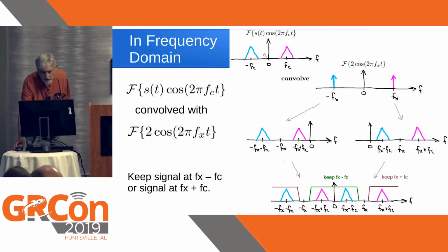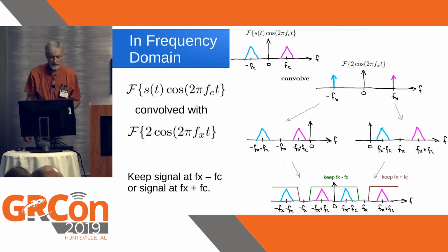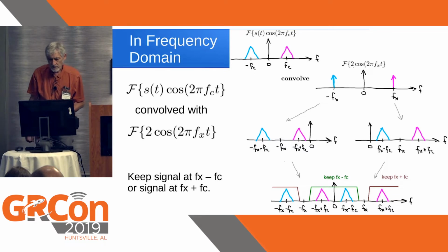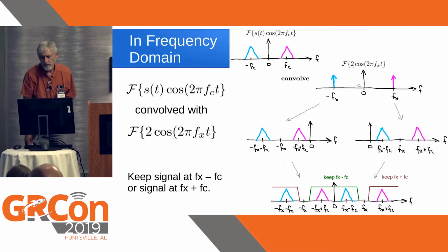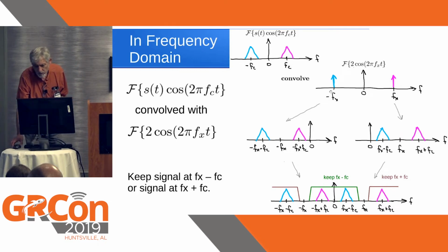Up here is a signal that sort of represents graphically what could be a radio signal. And I used different colors for the positive and the negative frequencies so that you can see how this combines together. And then you multiply this with a mixer, which is just a sinusoid. That mixer in the frequency domain is just two impulses. And you convolve those things together so the actual radio signal just gets placed to where the impulse is on the right side and on the left side.